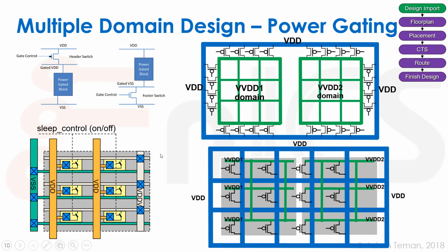So how are we going to do that? There are several ways. The two primary approaches are to do it in this outer gated style, where we'll put the switches, which are all parallel to each other, around the domains. That's really nice from a floor plan concept, because we can just do our regular place and route inside the different domains, and we just have to treat the switches outside and route their signals to them outside the actual floor plan of this part.